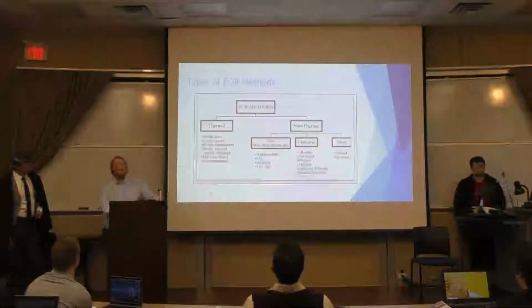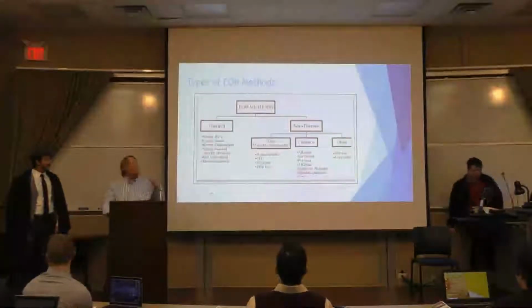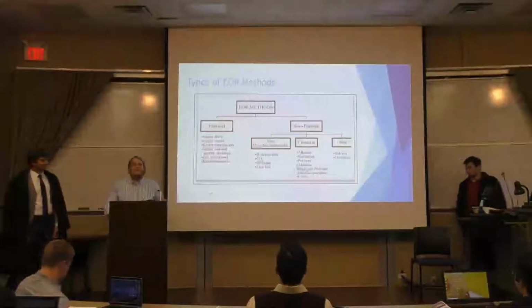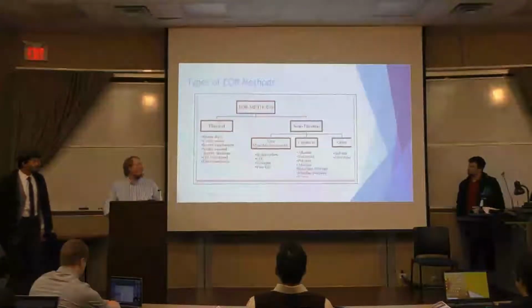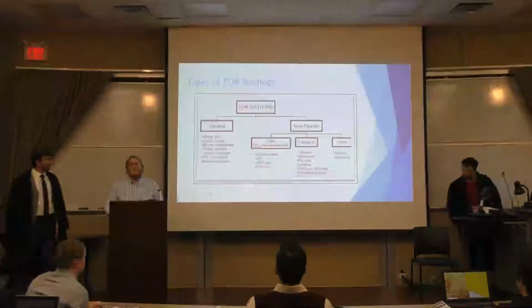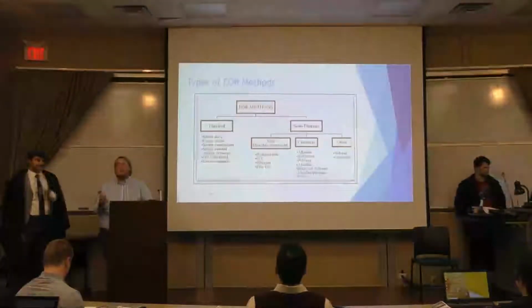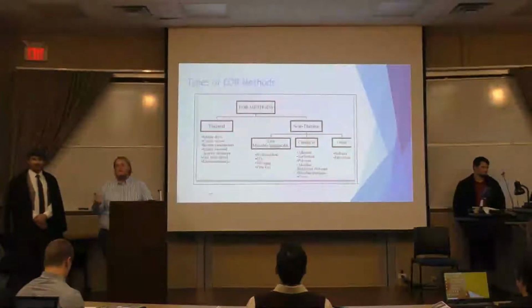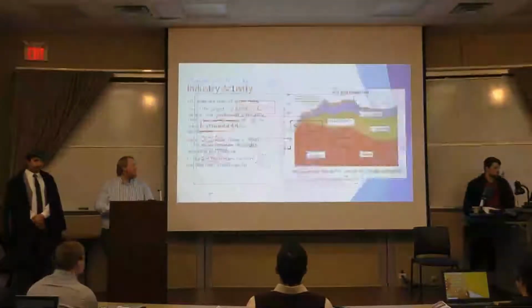Okay, so just a few types. You have thermal and non-thermal EOR. Thermal EOR, as they so lovely described, is increasing the heat to increase your recovery, decrease the viscosity. Your gas injection on the side, chemical injection, and microbacterial injection, all are used to change the composition of the oil downhole, and that'll allow you to decrease mobility ratios, increase mobility, allow for easier flow downhole.